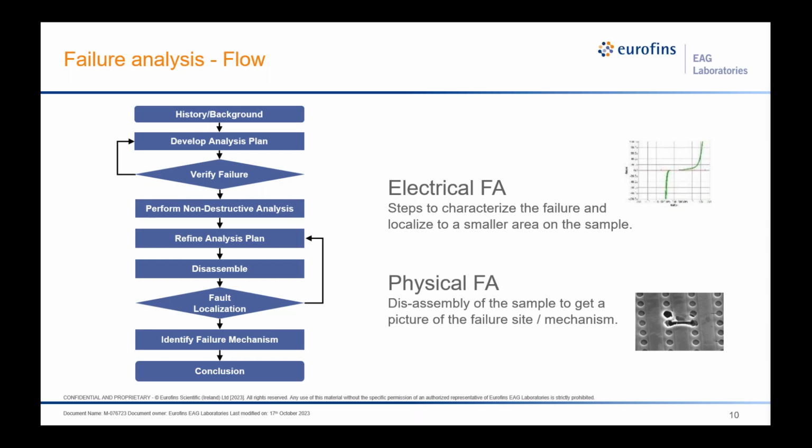So the electrical failure analysis actually starts with things like verifying the failure, whether it be on the bench or on an eval board, maybe an ATE data log, some basic IV characteristics and curve tracing. That falls into the electrical failure analysis, EFA, which would be the initial portions of the work. It also encompasses some of the fault localization techniques, which we'll maybe touch on later, but these are techniques to isolate the failure down to an XY position so that we can enable the next phase, which would be the physical analysis, the PFA.